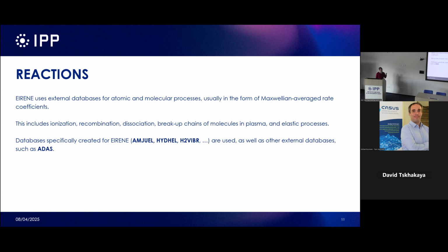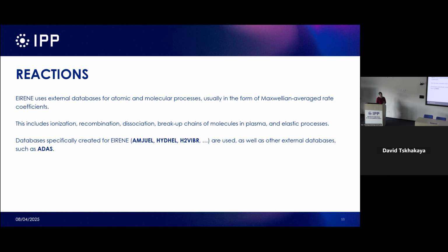Basically, it samples some distance from the distribution, and it calculates where the position will be, and that's where the particle will be. Then an additional variable is allocated to the given marker, so it's a counter for each marker. Yes. So you have a collision, let's say, and then this counter starts to count: okay, it traveled 1 millimeter, 2 millimeters. If it should collide in 1 meter, it really keeps adding this distance.